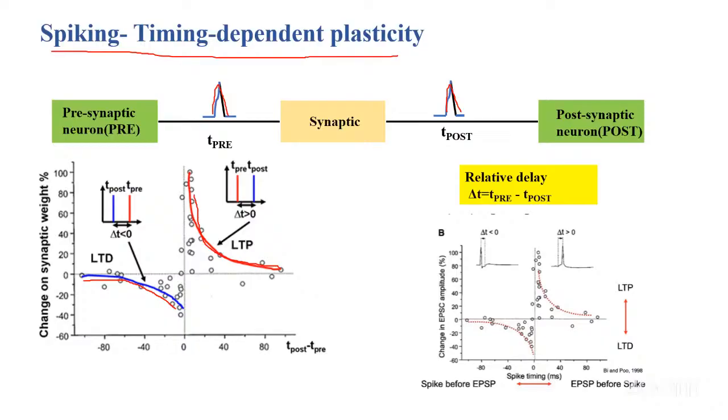So you need these properties to be mimicked in a synapse, and this property is called synaptic time-dependent plasticity, where the temporal variation of pre and post synaptic spikes decides the change in conductance or synaptic weight of the memory element. So these results are from RRAM, one of the papers from RRAM. This is not ferroelectric, but the ferroelectric FETs also have these properties.